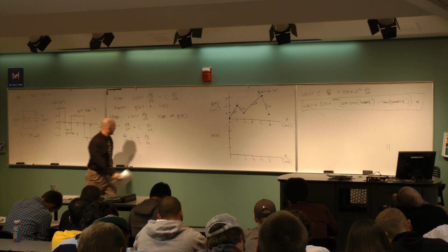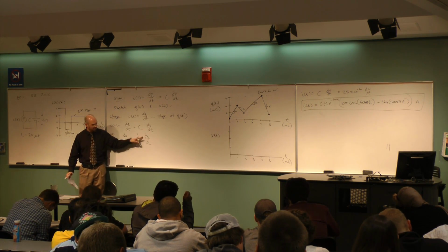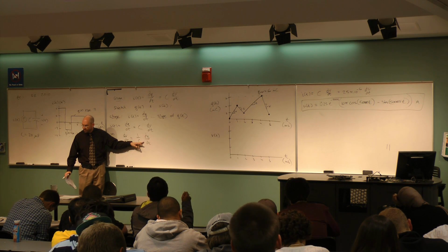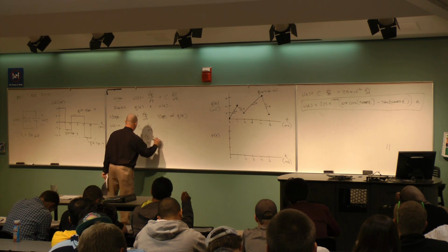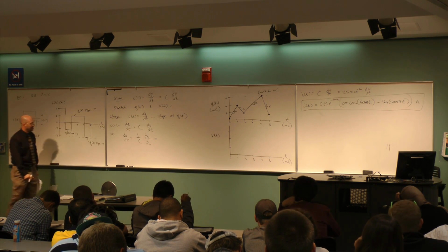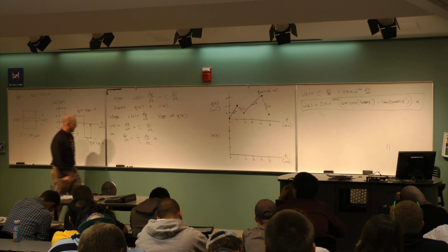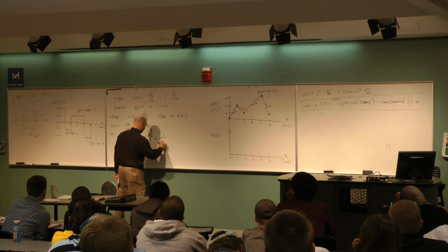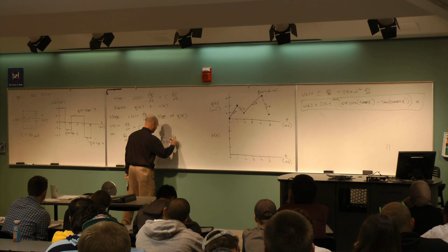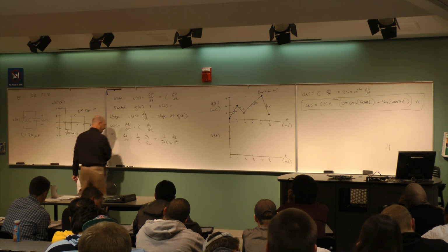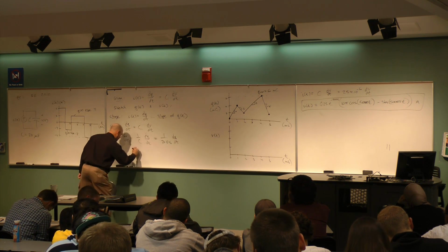So I'm going to take the same plot, but the slope of every one of these lines is now multiplied by 1 over C. How much is C? 20 microfarads, right? 1 over 20 e minus 6 times dq dt. What's 1 over 20 e minus 6 equal to?